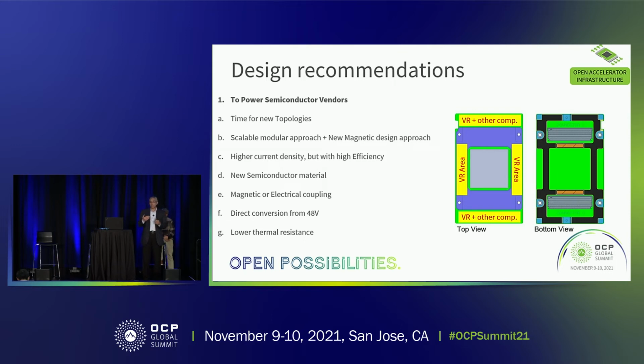People say, okay, we need to switch at higher switching frequency to improve the magnetic, but magnetic is not the only factor, but also the semiconductor material. To switch at higher switching frequency, we need to look for a new semiconductor material. Why not look for wide bandgap material that allows us to switch at higher switching frequency? Always, silicon is impacting the switching losses when we go to 1, 2 and 3 megahertz. Okay, let's look for a different semiconductor material, wide bandgap, enabling higher switching frequency.